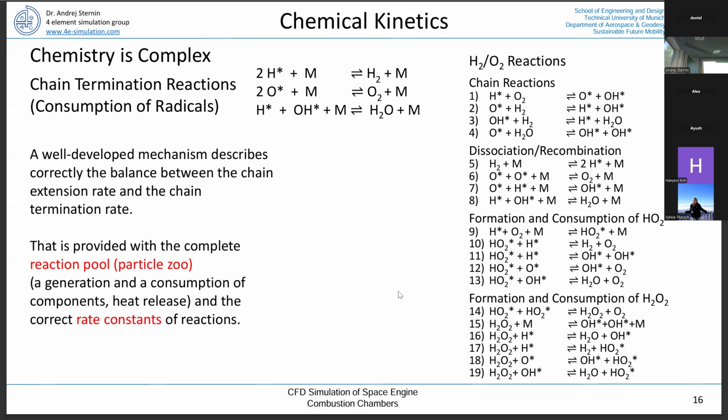The reason why this is important is, if you recall what I was mentioning, that in a rocket engine in the boundary layer, we are lowering the temperature because we have to cool the wall. Since we change the temperature as we go nearer to the wall, we change the local conditions, so we may have different kinds of reactions. For instance, there could be some sort of recombination.